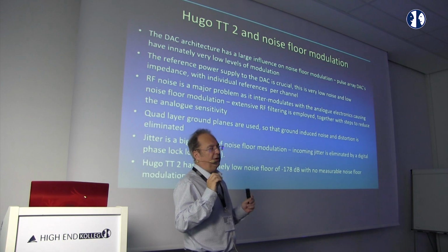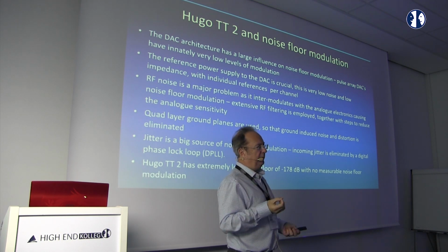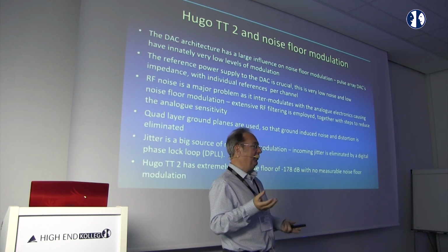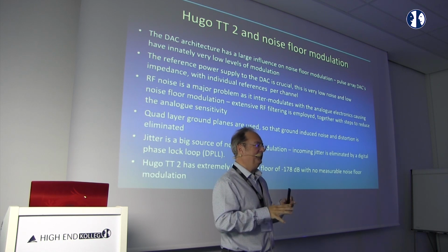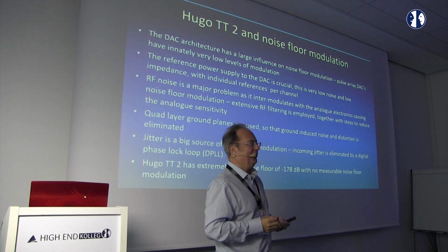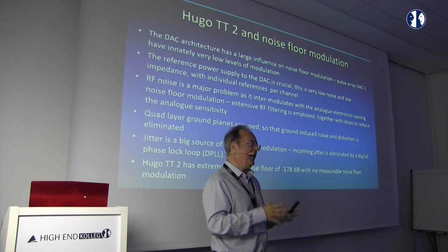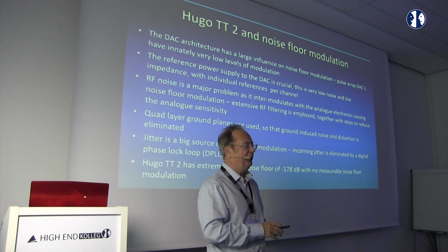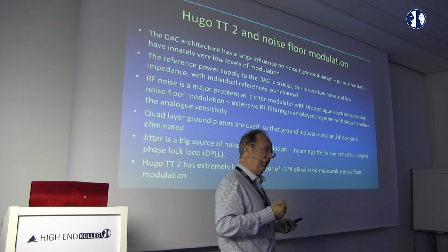What people don't appreciate is that you can design a DAC to suit any jitter requirements that you've got. In fact, there's one silicon chip design that I was working on where the original specification said we want it to work with 4 picoseconds worth of random jitter, and we want 120 dB performance. I said, fine, we can do this. Here's the design, after a suitable period of time. They then turned around and said, oh no, we've got our calculations wrong. We want it to be 15 picoseconds worth of random jitter, because we think the clock activity rate is going to be pretty poor and there's going to be lots of corruption from inside the chip. So I said, fine, okay, we can change that. Here's the new design. And the new design will work to 15 picoseconds with that level of performance. So you can adapt the DAC architecture to suit the jitter requirements that you've got coming through.